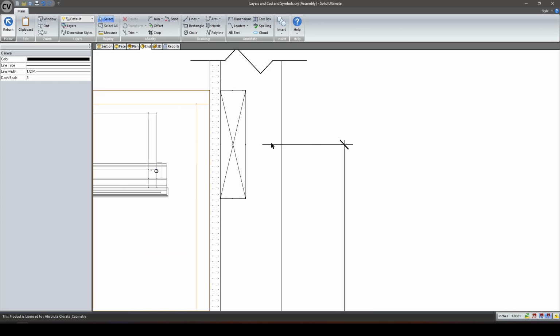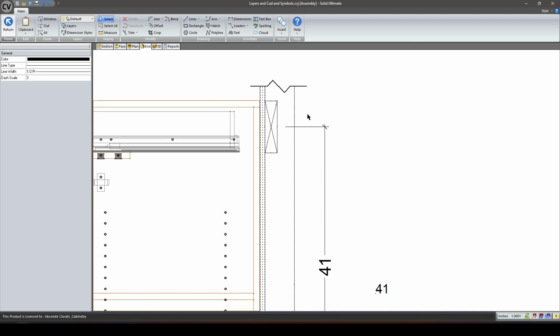So what I had done while I was working for that shop was I dimmed a bunch of lines with a UCS. And so I kind of tied a UCS in with my section details. And what that ended up being was a black line, so like dim black as a new part. And I would just set the thickness of the line to 0.001, the width of the line would be 0.001, and the length of the line would be whatever my typical shop drawings dimension from here to here would be.